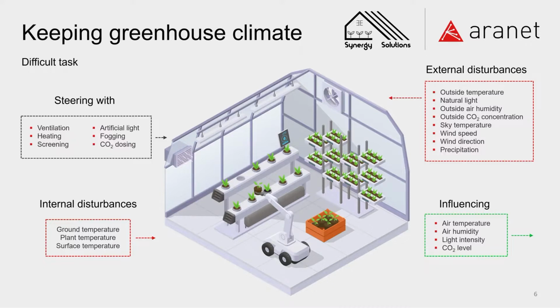If you see that at your crop one sensor is reading one temperature, and your climate computer is reading another temperature, it is already an alarming point that you need to check which one is showing right. For that we often test with calibrated sensors to check temperature and humidity, and we see that temperature readings in different places of the greenhouse are different, but the sensors usually are measuring right. But you need to decide what you're going to monitor, and then apply your steering possibilities in a climate computer to achieve the climate that you want around your plants.